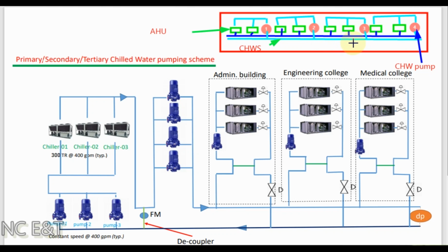This chill water pump is a set, one operation, one standby, and serving the group of AHUs after it. This group of AHUs normally is 2, 3, 4 or 5 AHUs. The same arrangement will be provided in the mechanical area that we create throughout the length or throughout the perimeter of the large building.